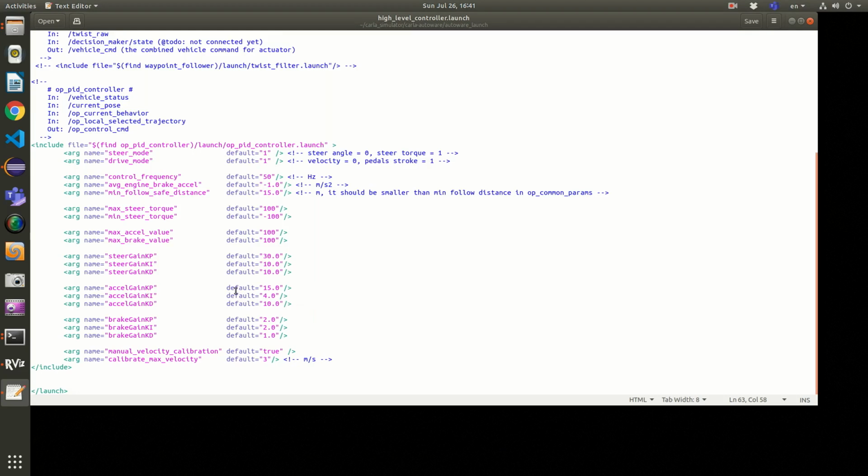Here in the acceleration PID, we can see that the differential gain is really big. What if we make that a smaller value, like 3 or 2, and run our test again and check? This is how PIDs are tuned.